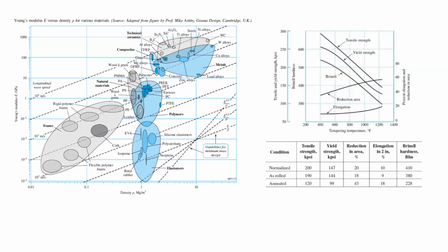In contrast, as you anneal or heat treat a material in any way, in general, if you make the material stronger, you're also going to make it more brittle for metals. So that's the most important relationship that you should be aware of. In some cases, you'll need the enhanced yield strength, but in some cases, you want the ductility for reasons such as having detectable failure without it being too critical.